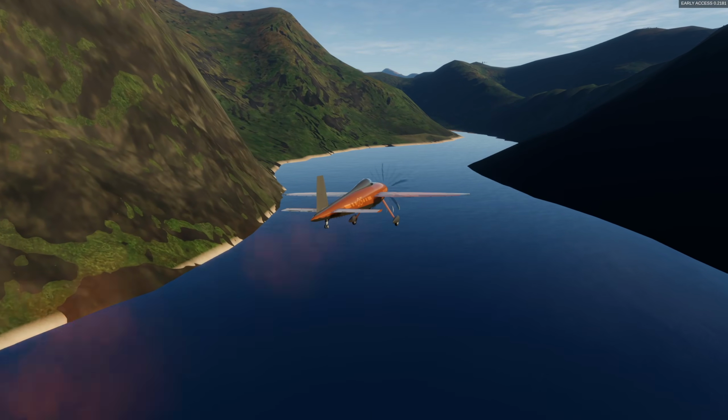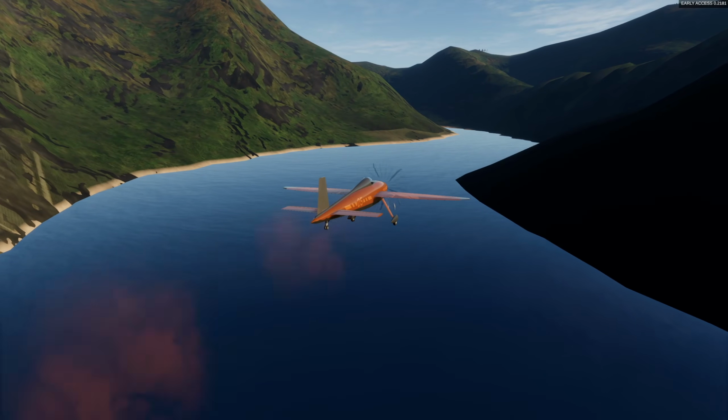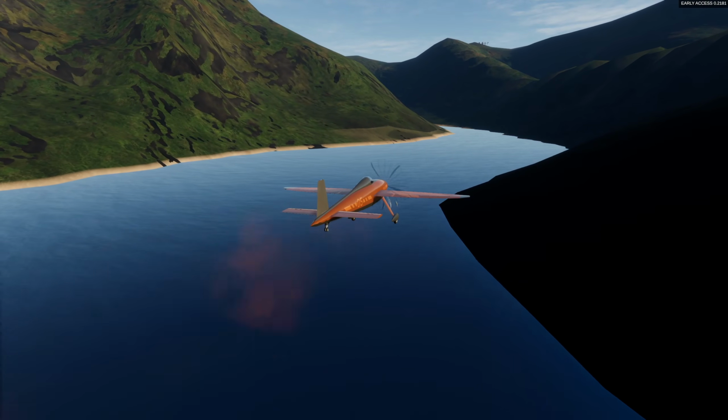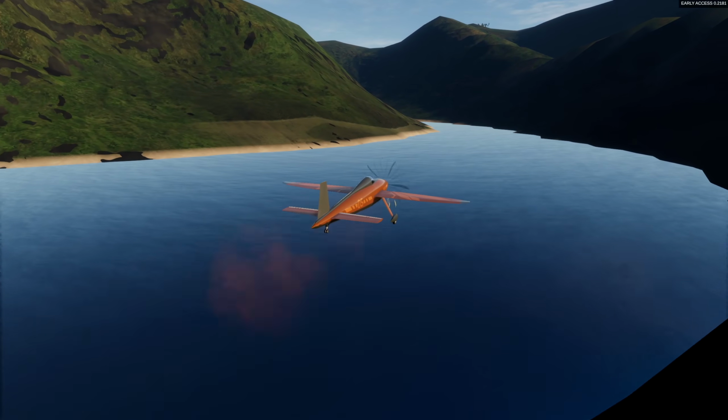If you can't get your propeller up to speed with your current settings, you likely need to decrease your propeller's weight by either decreasing size or blade count. Changing size will require you to recalculate your gear ratio.